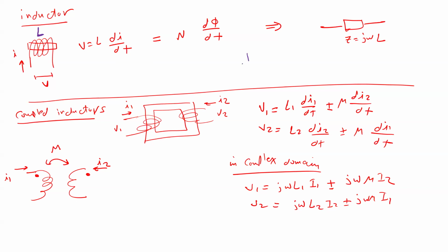There is a big difference between capacitors and inductors on one hand and resistors on the other hand. As you will understand better in the coming chapter, resistors consume energy. However, inductors and capacitors store and release energy. They don't consume. They store and release. Okay. Anyway, we are also familiar with this one here. The voltage across the inductor is equal to L dI/dt or N dPhi/dt.